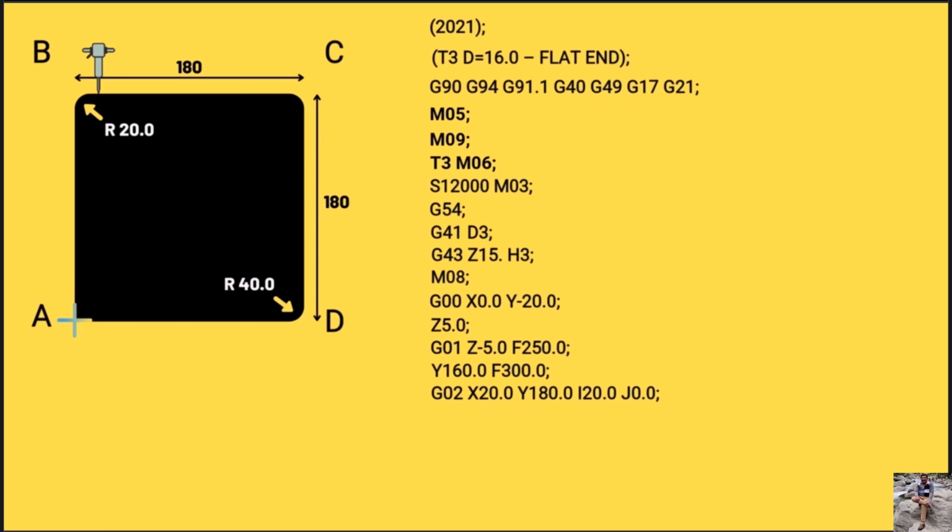Now, our next movement command is a simple straight line. So for that, we are going to use G01. We need to declare G01 here as the previous line had G02 already defined. During the first cut, we told the machine we were cutting the radial. Now, we need to tell the machine we are cutting linear again. So, we just need to give it an end point in the x-axis, and we don't need to tell it the y position because it assumes it's not moving in y if we don't give it a dimension.